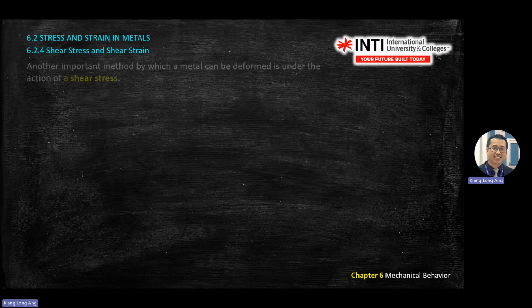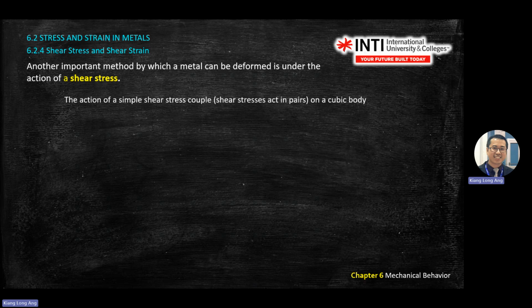Just now we learned about the normal direction. Now we go into shear stress. Again, if you see the word shear, remember the direction: the force is parallel to the surface. You learned statics, you learned a lot of trigonometry, right? So let's say you are given a force with an angle. You know that the force can split into two directions, right? So this kind of force with an angle can give you a normal force and a shear force.